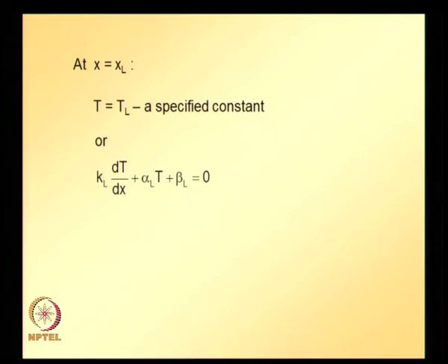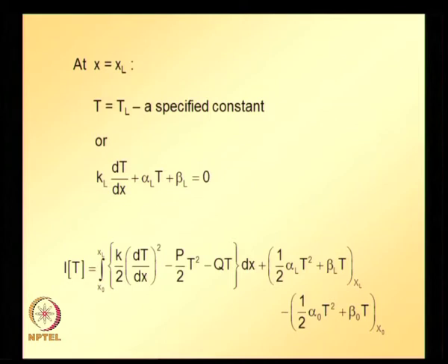So what we did is we applied the Rayleigh-Ritz method, and we found the equivalent functional before we proceeded and substituted finite element approximations in terms of a two node linear element, for T and the derivative of T. The equivalent functional that we obtained in the last class using the Rayleigh-Ritz method is given here, and then we substituted finite element approximations of T and also the derivative of T, taking a two node linear element.